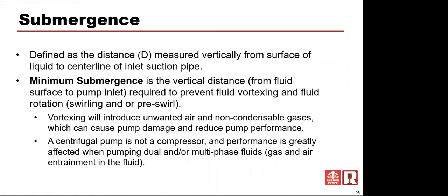Submergence: typically you want to stay at least one diameter off the bottom of the pump, or else you're going to start increasing the velocity if this is a vertical. The distance of minimum submergence is basically the measurement from the inlet suction pipe to the surface of the liquid. And it's very calculable.